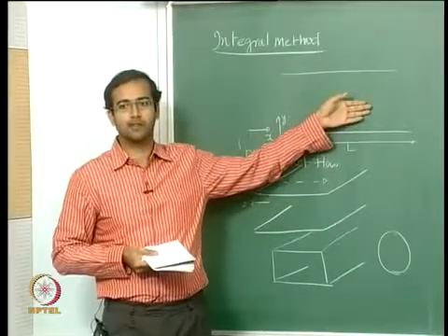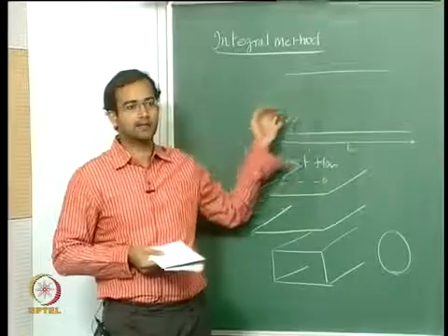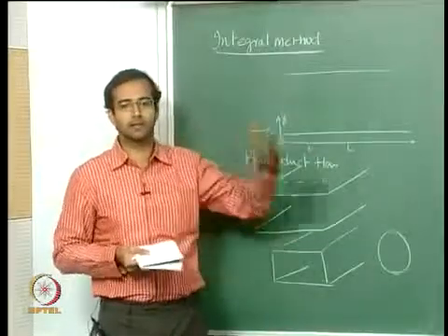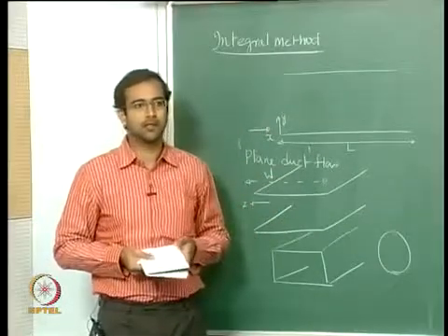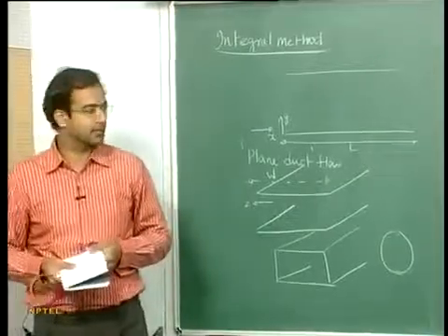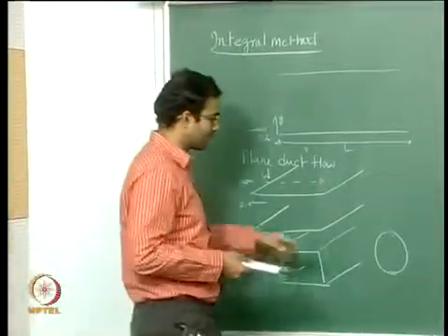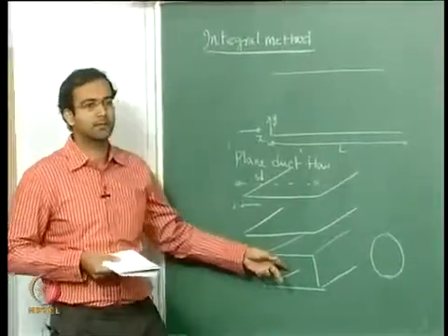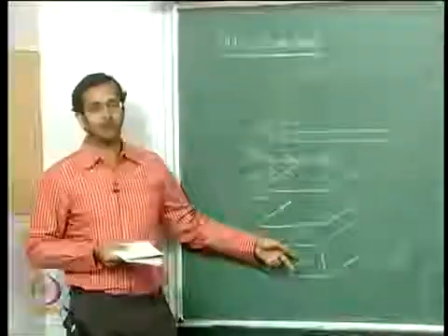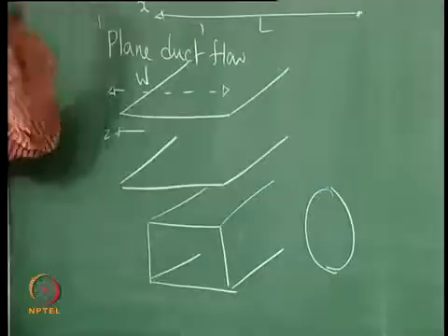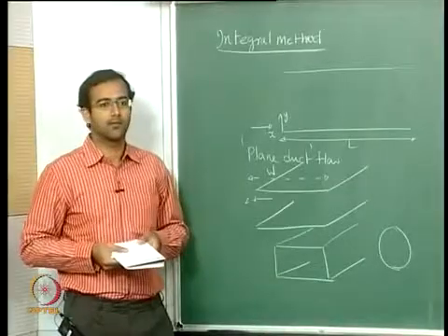If you rotate about the axis of symmetry, that is going to give you the 3-dimensional profile, and that's why they were called 2D axisymmetric flows. Now this is a 2D axisymmetric flow. However, this is not a 2D axisymmetric flow; this is clearly a 3-dimensional flow. You cannot rotate it about any axis and get the profile variation.